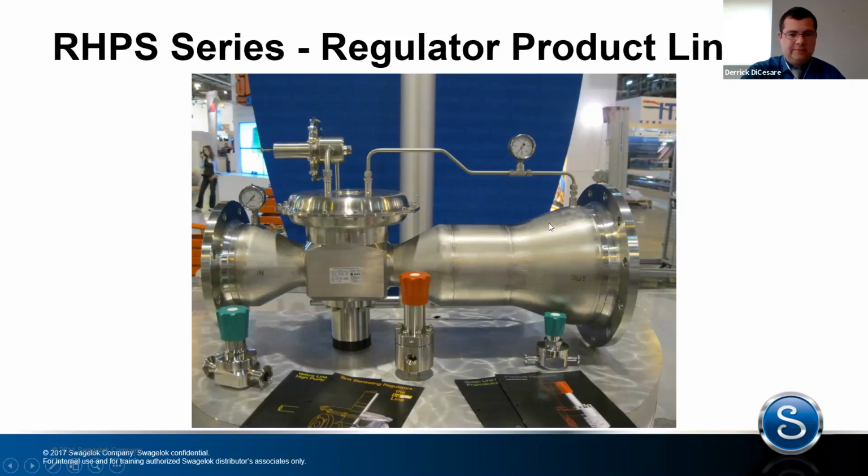This is a pretty niche application. But it can be done. We can weld this giant inlet to create the flow that we need through here to the outlet. And this is a low pressure application. I believe the outlet pressure is 10 PSI, but because of the flow, we need to size up the end connections to these enormous connections.